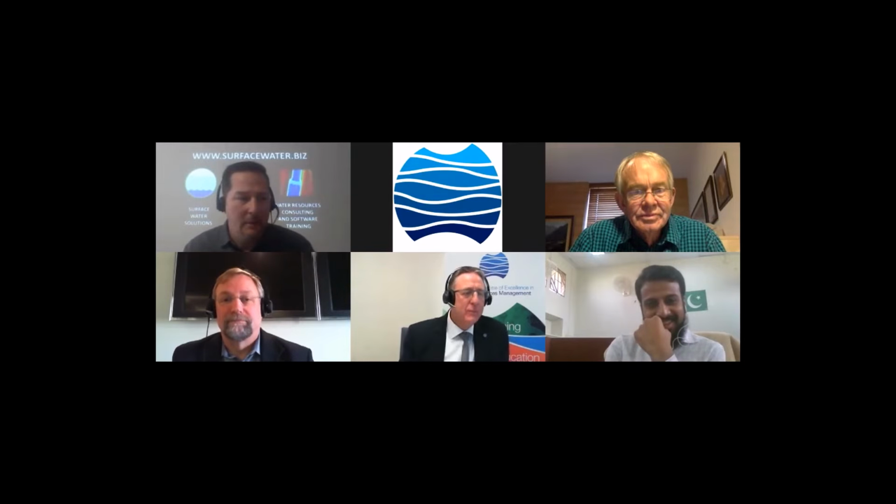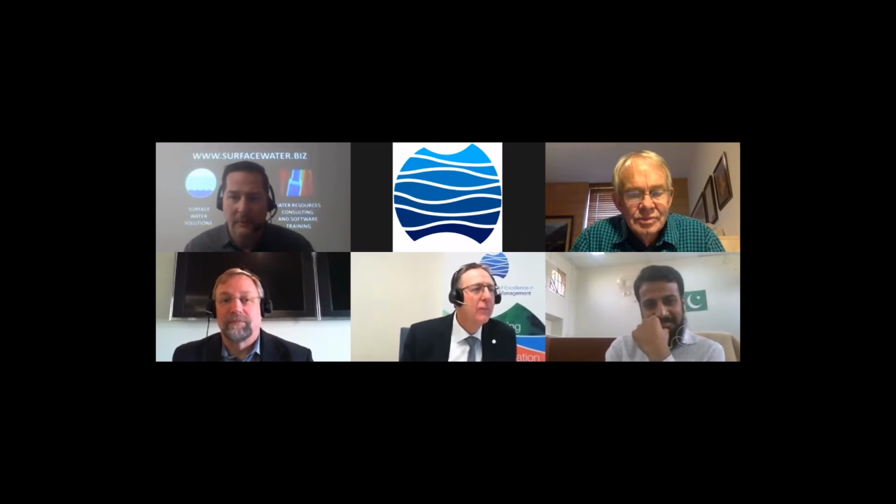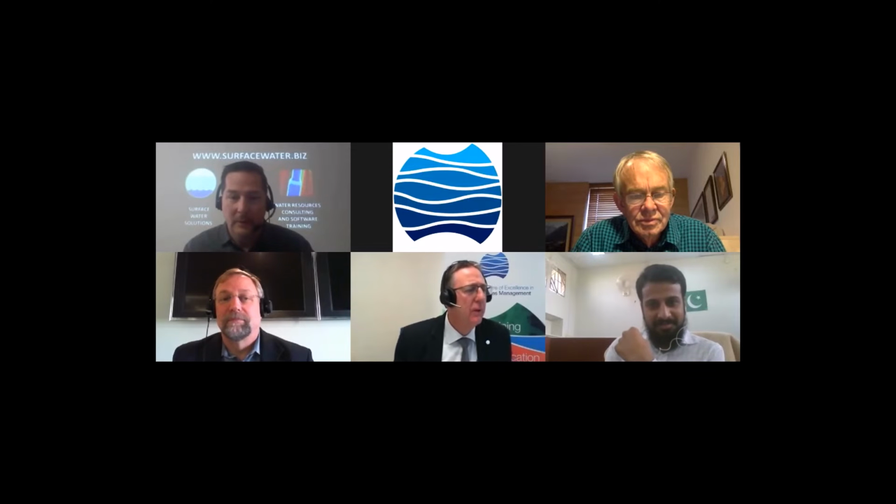Well, what I would say about that is, again, your model is going to be only as good as your data coming into it. And if you don't have good data, you're not going to have a good model. I tell my courses, I used to teach surveying courses, I can get better results if I go out with a hand level and a rod and a tape measure and Manning's equation on my calculator than with $100,000 worth of LiDAR data if that LiDAR data missed the low flow channel.